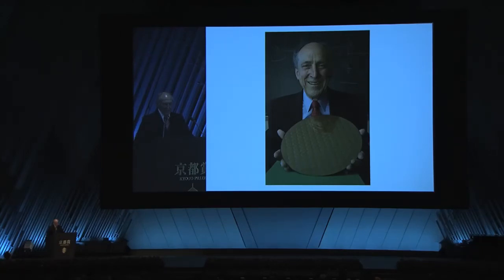As scaling progressed from one generation of chips to the next, the widths of all the wires were scaled down, along with the transistor dimensions, as the scaling principles we discussed earlier suggested. But this made the wires much more resistive for a given length of wire. Some of the wires which had to connect longer distances across the bigger chips got very resistive, and the signals propagated very slowly on those wires. Many people thought scaling was nearing an end because of this problem. To me, it was another crisis which needed attention.